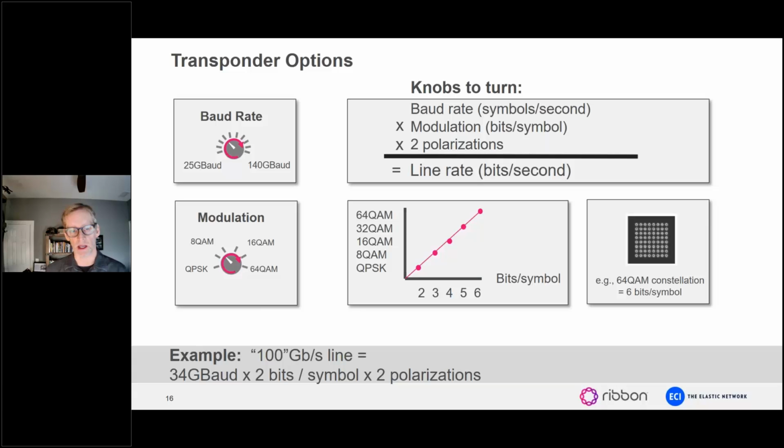And you can imagine now, if I'm a receiver and I'm trying to receive this constellation, it might get a little difficult for me to detect. The more bits per symbol I have, the more dots I have, it might get a little bit difficult to detect one dot from another dot, and that's where you get into errors. So you can really ramp up the QAM modulation and get more bits per symbol in your channel, but as that comes down the line, it becomes harder to distinguish one bit from another, so you can't go as far generally.